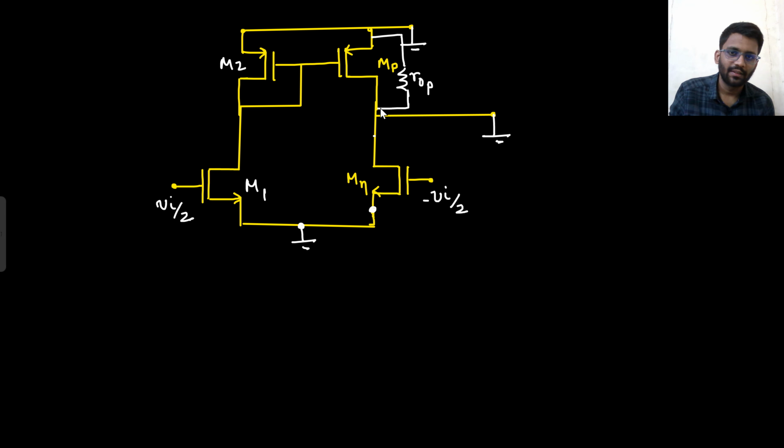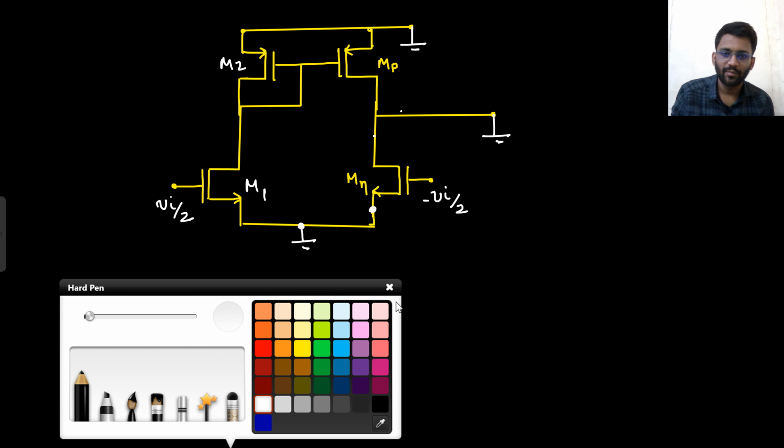And similarly, this R0P is also becoming between two grounds, so this will also be gone. R0P will also be 0. Basically, from here to here, this was your R0P, which is completely 0. Everything is completely grounded. So there is no effect of R0P and R0N now. Right? Now tell me what is the current here.